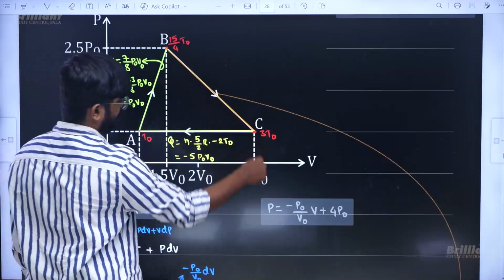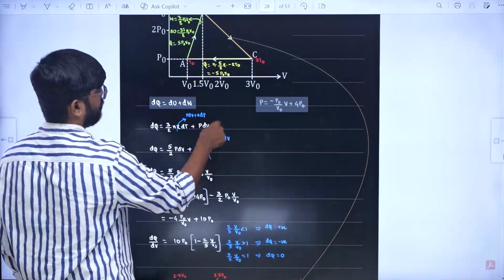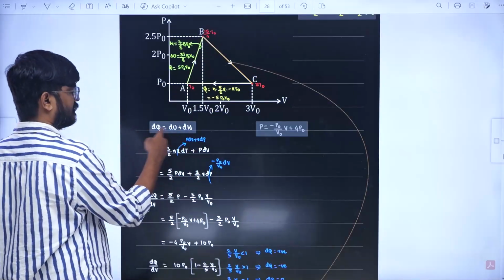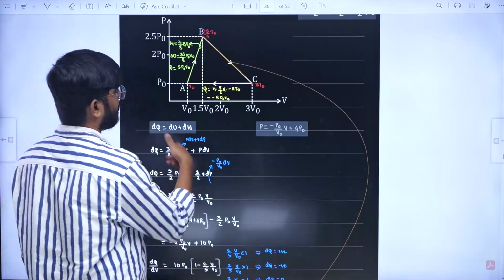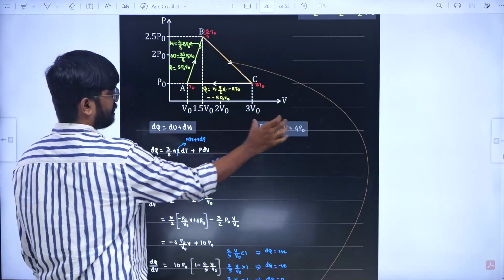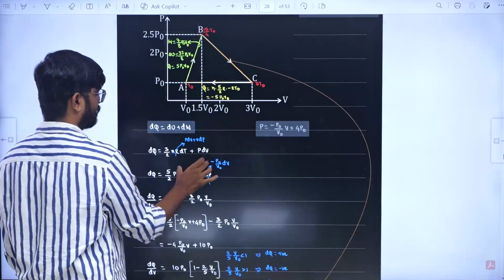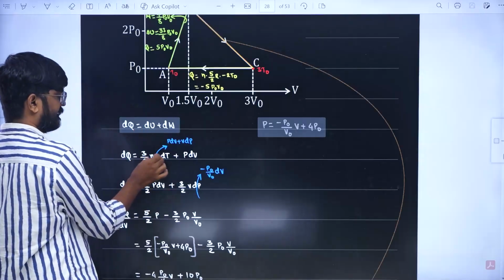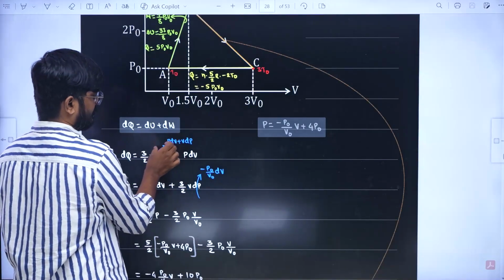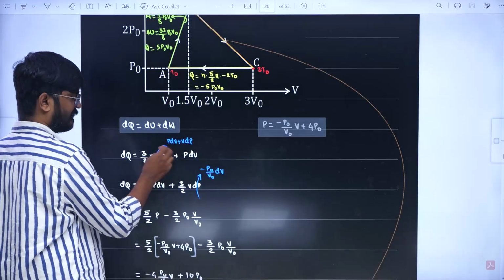So, we write this line equation, and energy conservation for any process is going to be this much. Now, we want to see where dQ is positive. So, for that, this is energy conservation, this is the line we are talking about. So, we will plug in this information back. dU is nCv delta T, nR dT I can write as PdV plus VdP by using gas law.